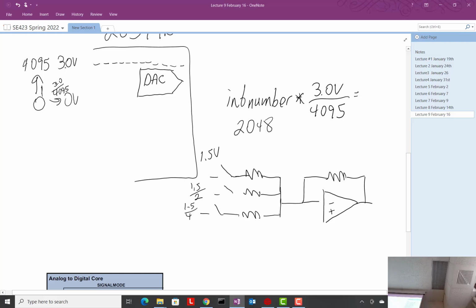You see what I'm doing? And I keep on summing all the way, so we'd have all these. And so the trick, actually, for the folks making a DAC, for Texas Instruments, whoever makes a DAC chip, is to get all these resistances to the right values precisely. So they laser trim these resistors to get it super precise and super linear.